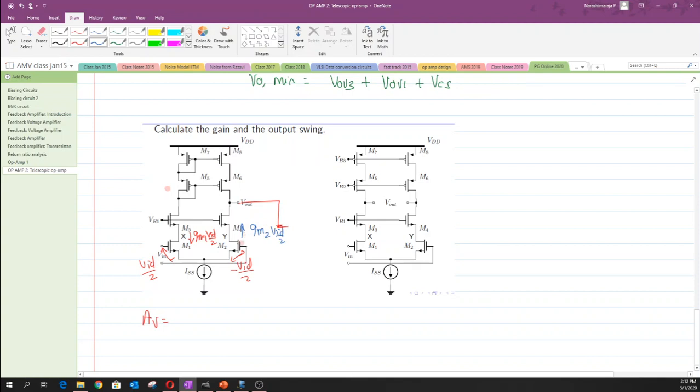Now, because there exists a current mirror structure created with M7 and M8, the current flowing across this M1 is reflected onto this path. That value would be the same provided we have the same aspect ratio for M7 and M8 and the same aspect ratio for M5 and M6. The details of these requirements have been discussed earlier, so I am not repeating them. As you can see, these two currents then sum up to a total value of I out.